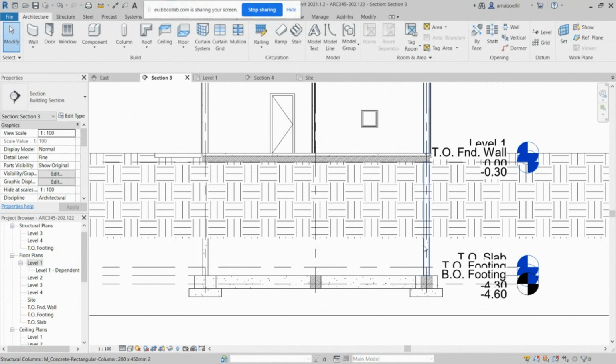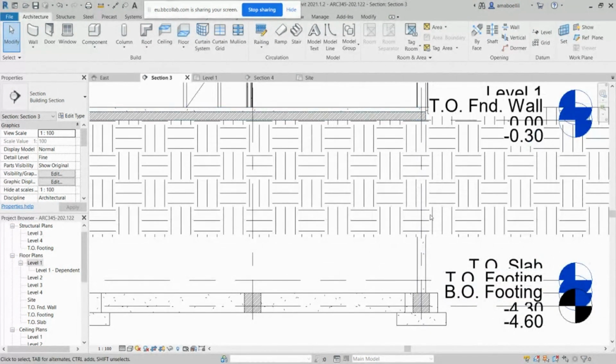Now the other thing that we have to treat is that you have to show the footings in your building, so that represents the plain footing, and on top of it we've seen the reinforced footing and the beams that are connecting it. Since I'm cutting in it, it shows to me like this. I didn't finish all of it, so that's why here it's not shown. But it's hidden behind the earth material that I have created here, so if you didn't do it in topography, you won't have a problem like this. If you do it in topography, you will see it hidden like that.